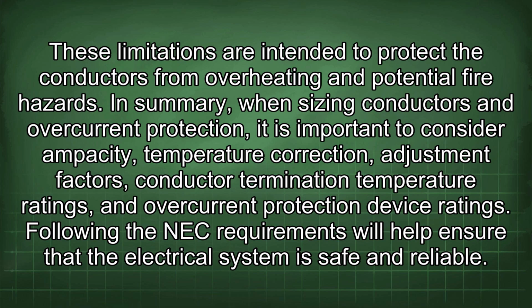In summary, when sizing conductors and overcurrent protection, it is important to consider ampacity, temperature correction, adjustment factors, conductor termination temperature ratings, and overcurrent protection device ratings. Following the NEC requirements will help ensure that the electrical system is safe and reliable.